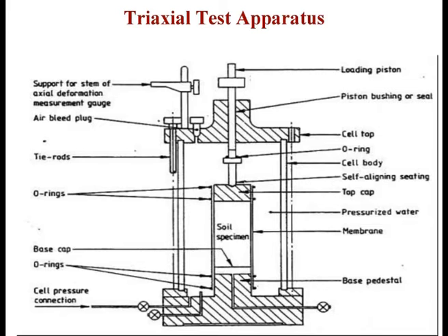So this is essentially what the triaxial test is all about. Now, you will remember that when we do a triaxial test, one of the things that we always plot is a Mohr circle. In a triaxial test, there are 2 stresses that are obviously important. The first is, let's take a compression test first. In a compression test, the vertical stress is also the major principal stress, right? The lateral stress is also usually the minor principal stress, and there's no shear stress. So there's only sigma 1, sigma 3.